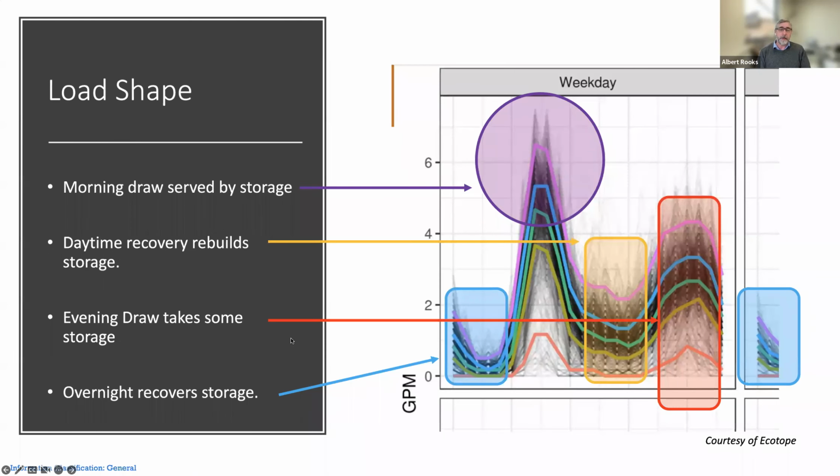As you size a day and establish how many gallons of hot water are going to be used throughout the 24-hour course of the day, it really looks like this. So maybe the first thing we do is, if we have that big peak in the morning, we really need to size primary storage at our full water temperature to cover that big amplitude of a peak. We can spend that low period in that goldish, yellowish square. We can turn the heat pumps on at any time as we start using the peak.